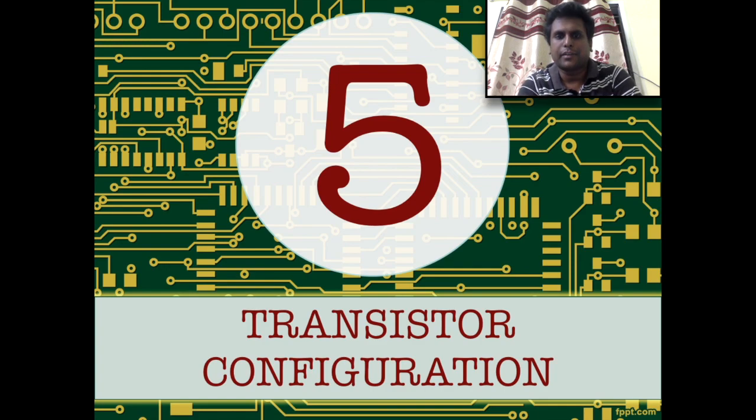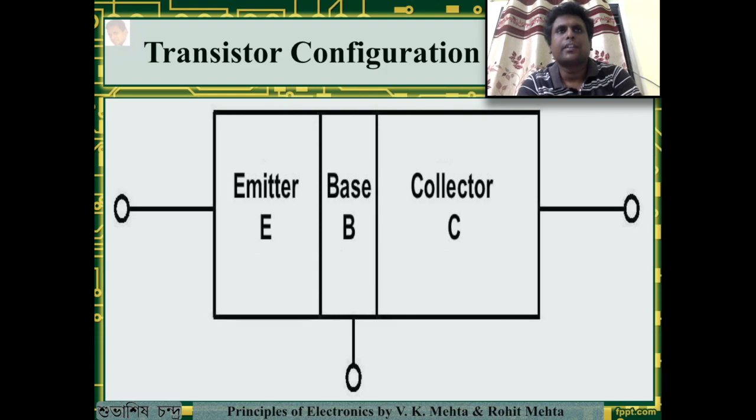our series. As we all know, every electronic circuit requires 4 terminals, 2 for input and 2 for output. The transistor has only 3 terminals, which does not fit the bill, and hence it was decided that one of the terminals would be made common so that the input can be provided between one terminal and the common terminal, and the output can be taken from the remaining terminal and the common terminal.